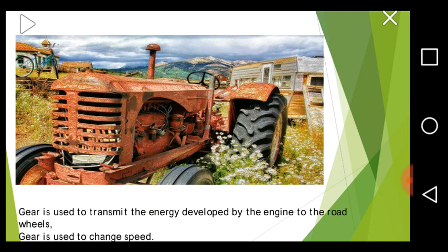And basically, there are two categories of gears. We have the driving gear and the driven gear. The driving gear is the gear closest to the power source and attached to the driving shaft that provides the initial rotational input, while the driven gear is a gear or tooth component attached to the driven shaft, which is impacted by the driving gear and exhibits the final output.